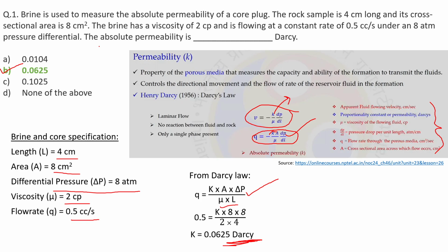But when we are talking about reservoir, as sir taught, in reservoir the flow of the fluid is supposed as laminar. So that's why whenever there is flow around the bore well and all in radial direction, they are considered as laminar. That's why for that Darcy law is used. But even if there is not a laminar flow, there is a turbulent flow, which in reservoir case is very rare. So for that there are other equations also, but that will be discussed later. But for permeability study, we need Darcy law and we assume that the flow is laminar.